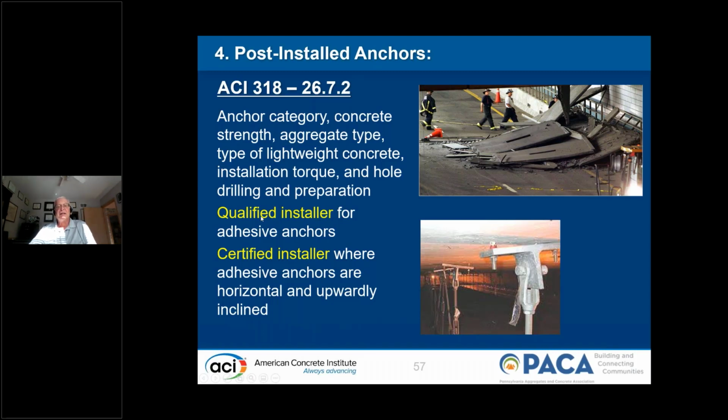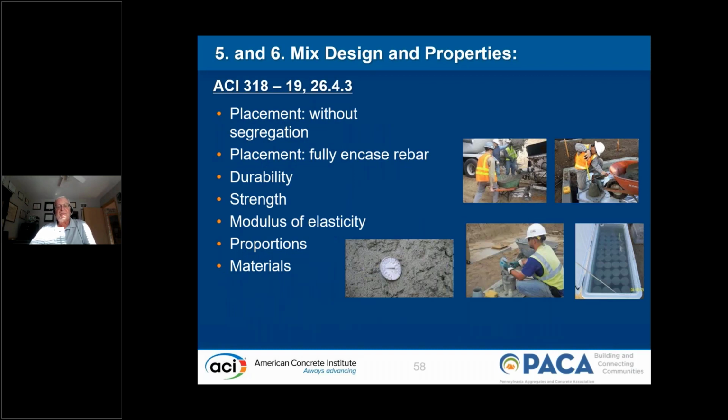So ACI 318 requires that the installer be qualified for adhesive anchors, and if they're horizontal or upwardly inclined, then they have to be a certified installer. And I mention these certifications because when it says certified, that means that's something that the building code official needs to be involved with to make sure that those individuals are properly certified, or get the information from the approved testing agency that demonstrates that these people are properly certified.